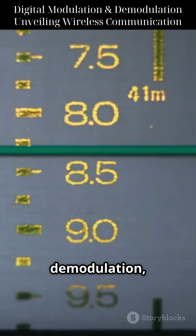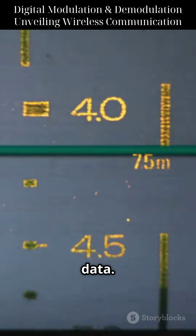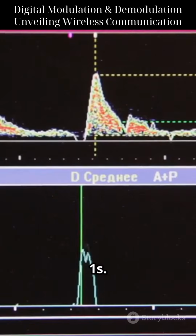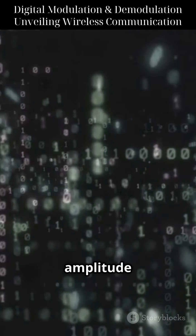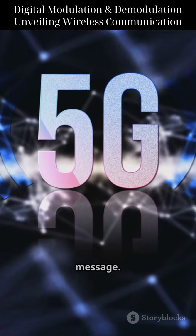In ASK demodulation, the receiver detects amplitude changes to reconstruct binary data. With FSK, the receiver maps frequency shifts back to 0s and 1s. For PSK and QAM, the receiver compares phase and amplitude shifts to decode data. It's like solving a puzzle to get back to the original message.